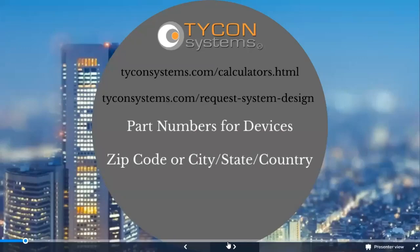And our design team will be able to help get all of the requirements for you and present a complete system design. To do this, we need to know the part numbers for all of the devices you're powering and the zip code or city, state, country that you are installing in. The reason for this is we're looking for the total power draw of all the devices. So we pull up the manufacturer's data sheets, find the total power draw and look at the voltage requirements, because manufacturers have different voltage requirements for each of their devices.